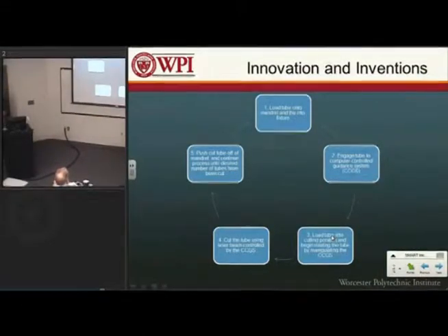So how we physically integrated this, we talked about a little bit in the decomposition, but the first step in the process would be to load the tube onto a mandrel into a fixture, and then we want to engage the tube with a computer-controlled guidance system so that we would be able to manipulate the location of the tube. And we want to load the tube into a set cutting position and begin rotating the tube, which will also be controlled by the computer system.